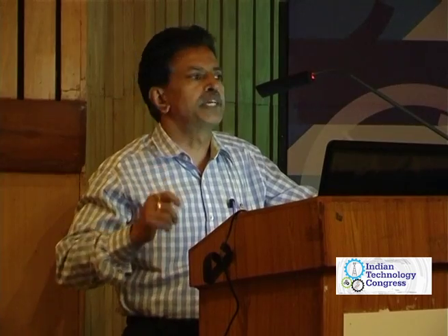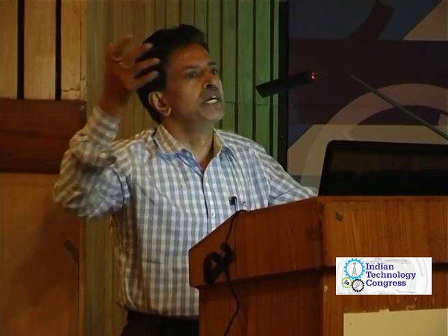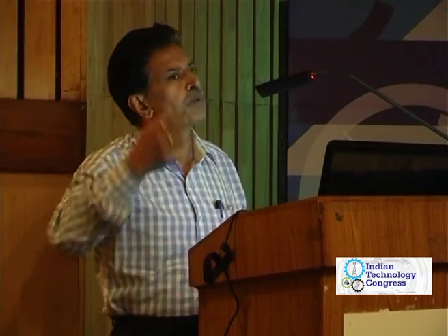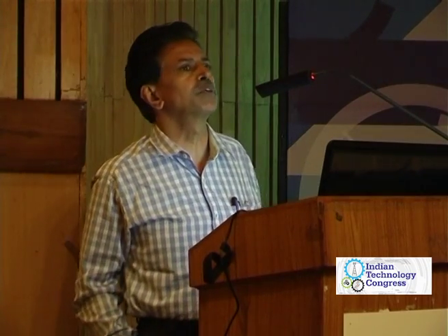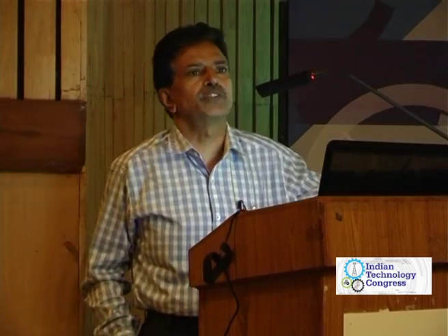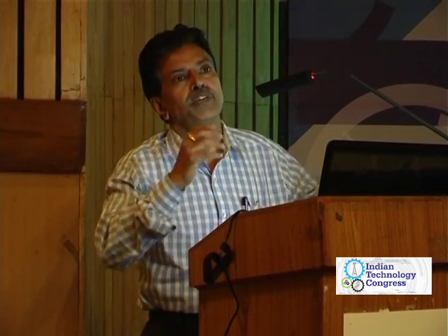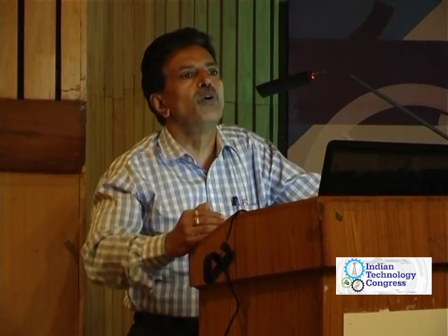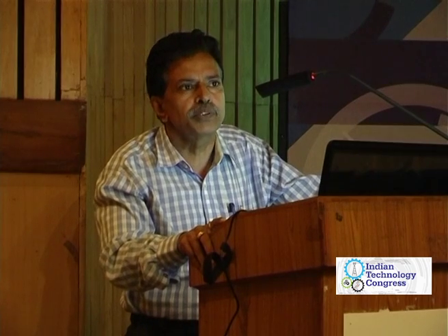How do you ensure that you get the best distribution? That's the challenge. It can be by powder metallurgy, it can be by squeeze casting. For the production route for the component, people are now trying to look at squeeze casting because we can go for high volume fractions. But processing is a very important route, because once you have the casting, you also need to go with the extrusion. Extrusion is a very challenging one for a metal matrix composite. And next comes the forging.